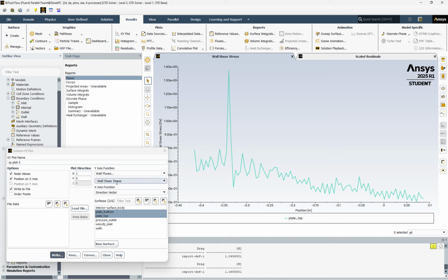And then along with that, I'm going to do the skin friction coefficient. It's not the worst. Could improve somewhat, but it's not terrible. I think it's just the meshing. That's why it's not as flat. It should be okay. Okay, so you've got the skin friction coefficient.